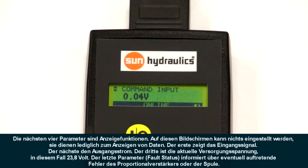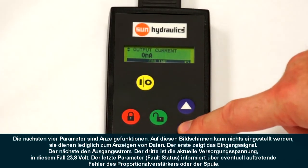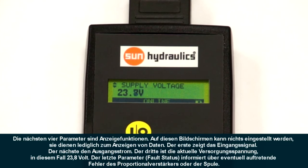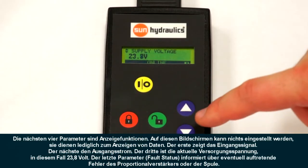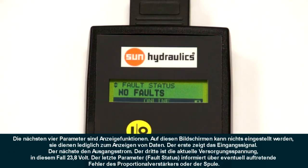The first shows the command input. The next shows the output current. The third is the supply voltage, with 23.8 volts in this case. This is the actual voltage being supplied to the amplifier. The last parameter shows the fault status and will list any faults with the amplifier.